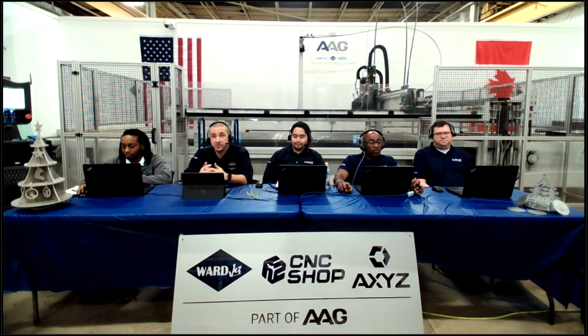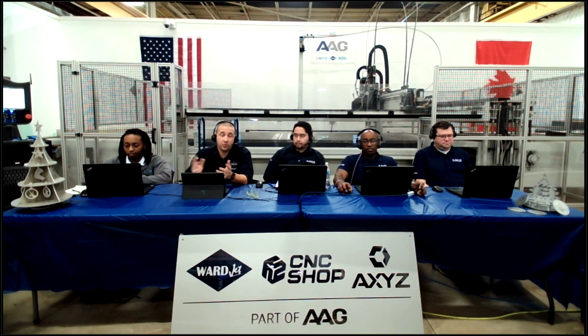It is going to process pretty slow. Again, kind of alluding to what Jeff mentioned earlier about those cut calculators. It may be a very, very slow process, but as long as we can get it under the head, we can get through it. Again, it's just going to be how patient you are and what kind of time you've got. But the good news is it is a single pass process, so you're not going to have to go over and over again. So you may only move about 0.01 inches a minute, but it will be a single pass. Kind of ideal for thicker material if you're doing near net shape.